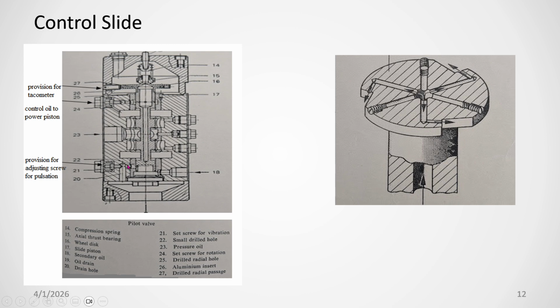So momentarily oil will come, then it will drain. Again momentarily oil will come, it will connect with the hole, and then it will drain. So this will go on fluctuating like this. It is a reciprocating motion plus circular motion due to this jet action, and then there is no question of getting stuck up. But once it gets stuck up, the valve will not operate.